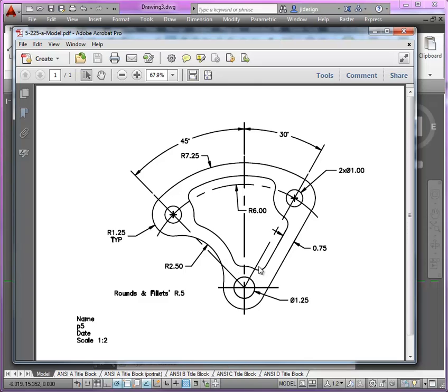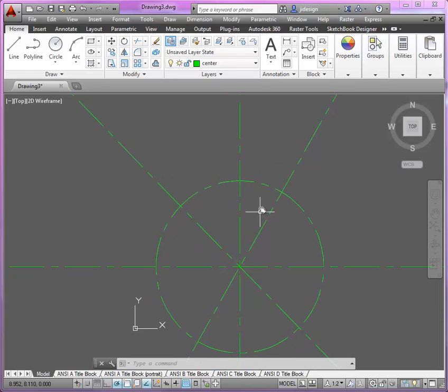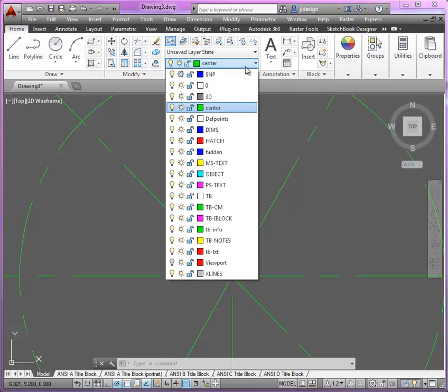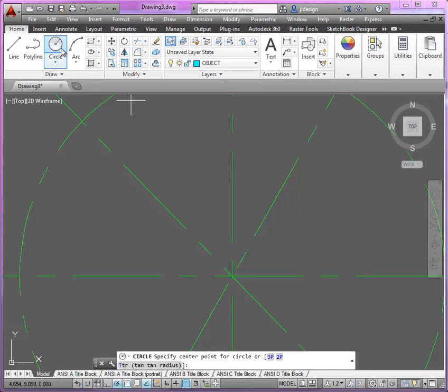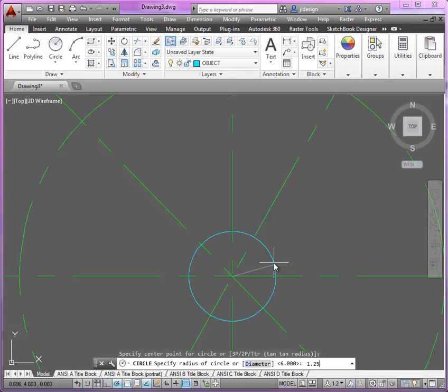So I'll draw your attention to these 3 concentric circles. We do have a pair here of equal radius and diameter, and then we have the one down here. I'm going to use the copy selection command to develop these sets of circles here, and then I'll show you using properties how we can modify our entities as well. So we're going to start down here at the bottom. I'm going to switch layers first and switch to the object layer. I'm going to select circle, and we're going to start first with the outer circle of radius 125. So we'll start there as the center, type in 125,